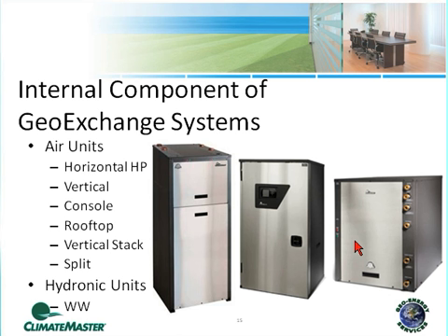On the right side here, we've got a standard water-to-water unit that ranges in capacity between 2 to 3 tons up to about 5 to 10 tons. And these have a variety of uses for radiant floor heating systems, domestic hot water heating, things of that nature, or small HVAC systems. You know, if you still want to do your air handler with VAV boxes, if you've got a 5-ton or 10-ton building or something of that nature, these little water units here could work well for that. I've typically used them for radiant floor heating systems, both commercial and residential, and I've used them for commercial hot water, domestic hot water heating projects as well.